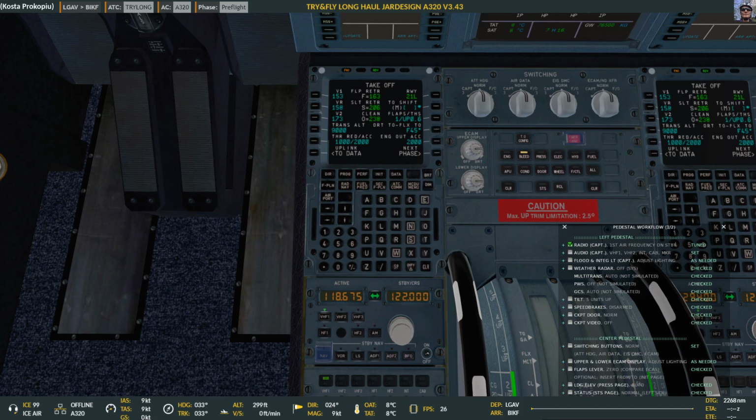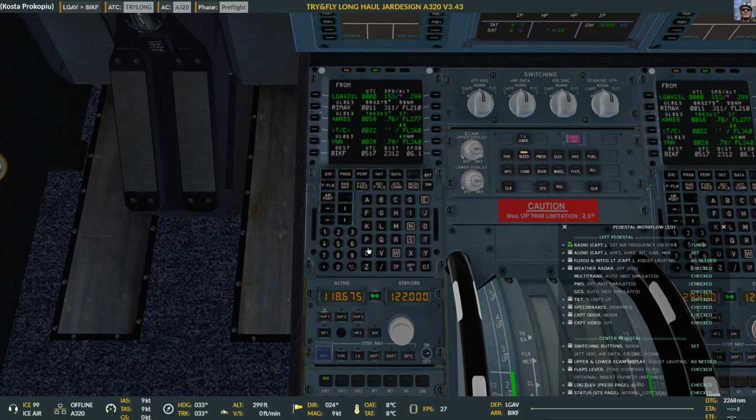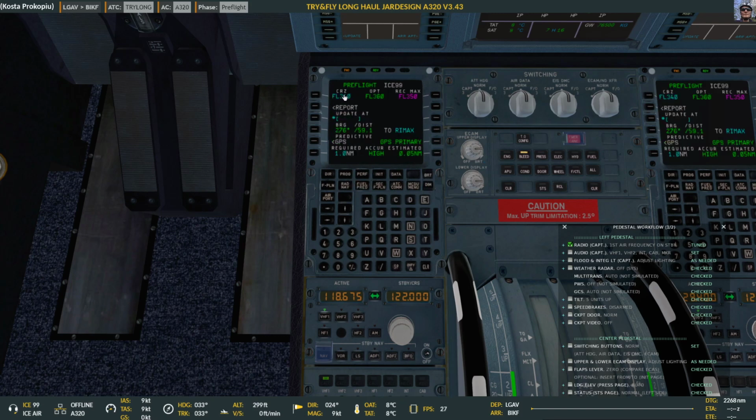Okay, so airport via the Bang 2 departure. That's the performance, so I think we're through. I'm not going to change anything here. I leave that all in standard, and Endeavour 3366 cleared via the Bang departure. That should do it for us. Flight level 340, optimum is 360. We might actually be going up later. Yeah, depends. I'm going to check the weather en route as well, just in case. So that basically does it,